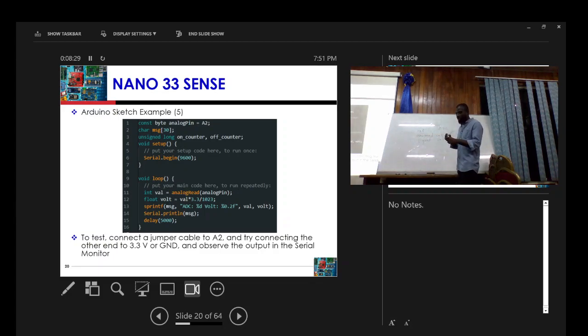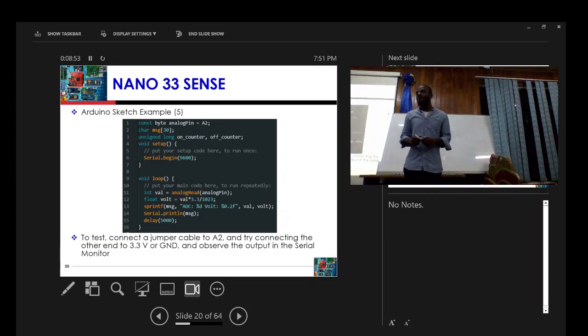So now we need to know the limit of where we can go. All the signals that fall above the limit of the ADC will be chopped off, and all the values that fall below the ADC range will also be chopped off. The ADC has a range. So here, this formula, this 1023 here, means that our values can range from 0 to 1023, right?